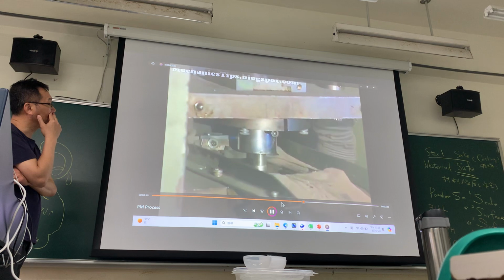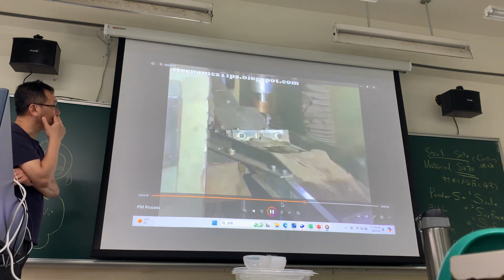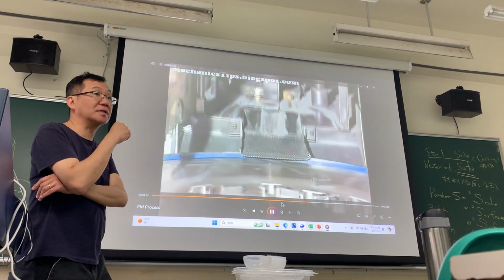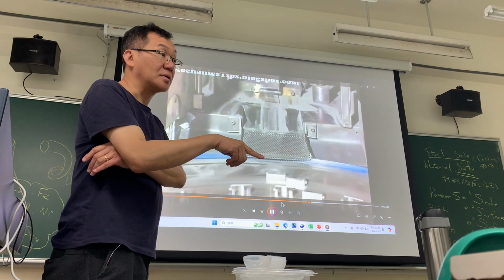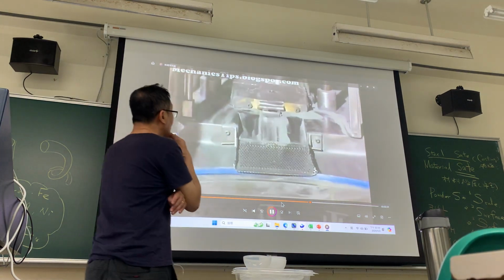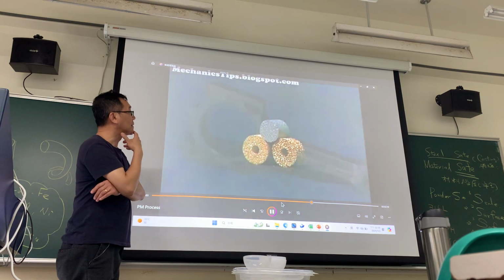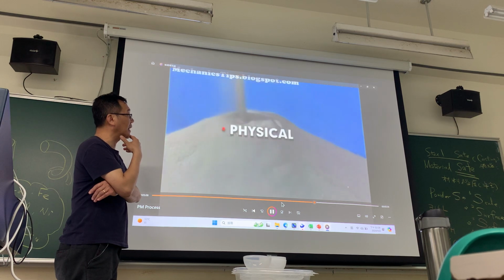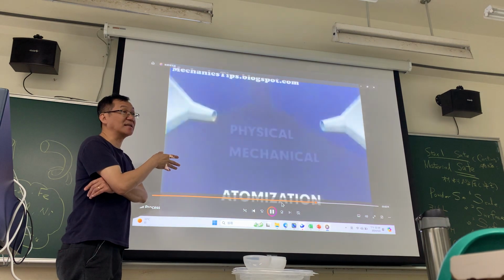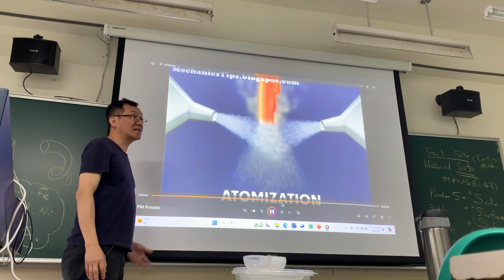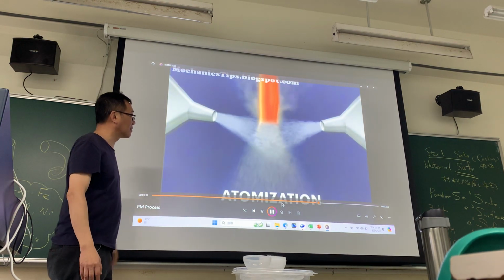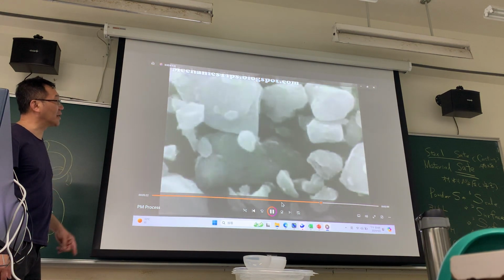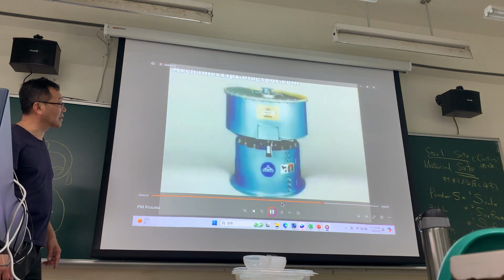Powder metallurgy is a metalworking technology used primarily for producing parts from metal powder. In this class, this one is the powder metallurgy principle. Parts can be produced in net or near net shape, and to control porosity or nearly full density. So PM is very cheap and very high speed, better than casting. Because casting is very dirty, this one is more convenient. Mechanical methods include milling in a mechanical way, rod, ball, grinding, or attrition mills.